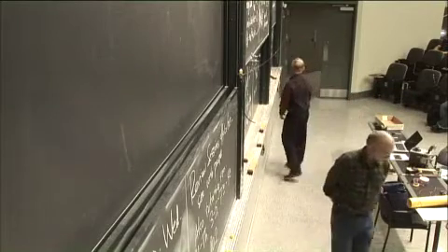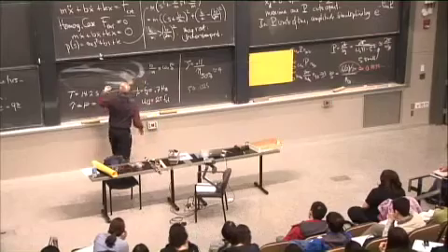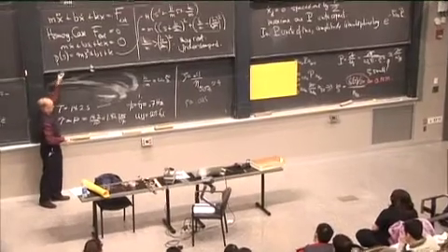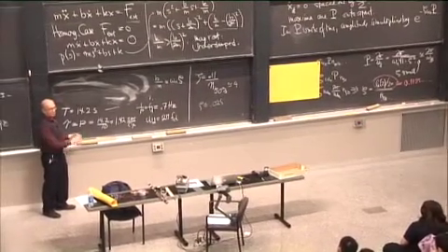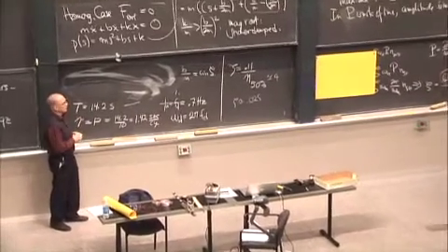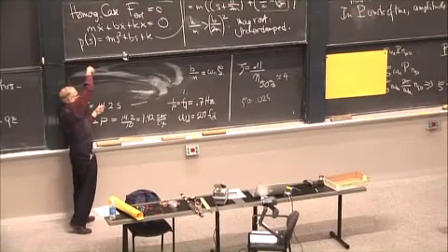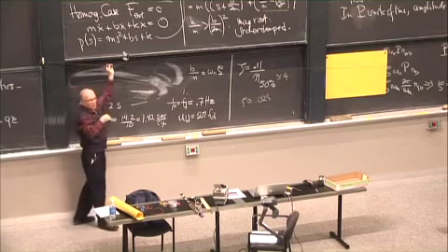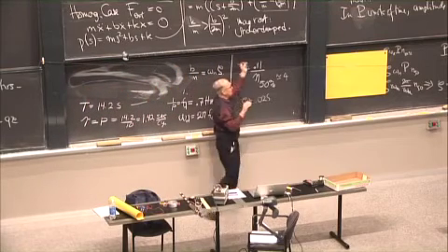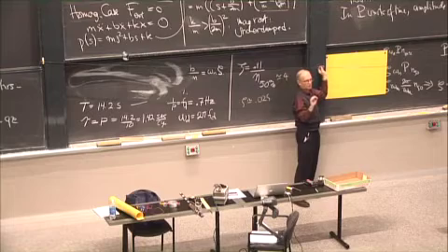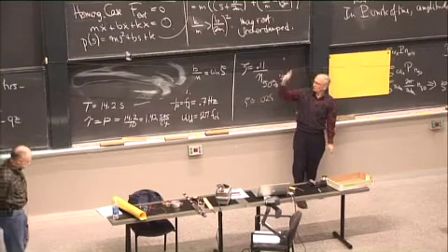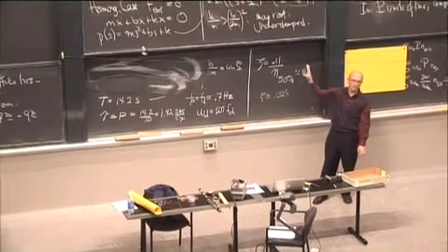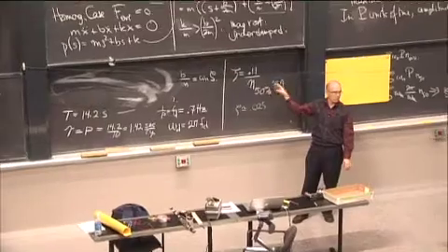So the string, when it vibrates, is like a guitar string or piano string. In its first mode of vibration, it looks like half a sine wave. And that's when you pluck your guitar string, that's the dominant sound you hear. But it has other natural frequencies as well. There's one. So it has many modes and many different frequencies. But any pure vibration at one of those frequencies behaves exactly as the simple oscillator equation. So we can use the conclusions for the simple oscillator equation to characterize things like the damping.